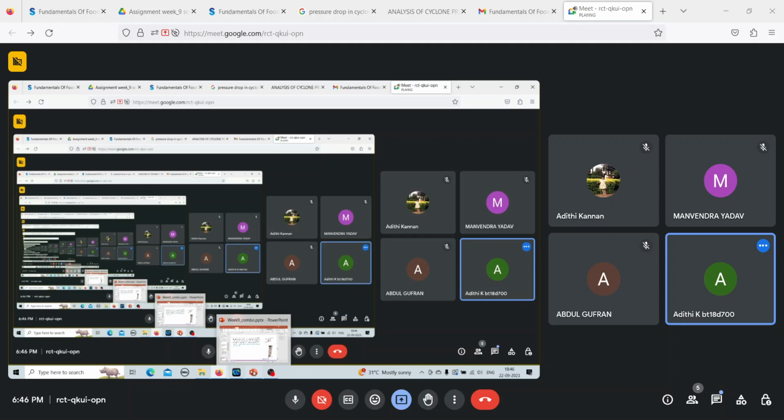So just to give a small recap, upon centrifuging, your liquid will be thrown out towards the walls. So the center will not have much liquid at all. So your liquid is present only from Ri to capital R. So in order to calculate the pressure at the walls, you first calculate the centrifugal force for a small region of the liquid and then integrate it from Ri to capital R. This will give us the pressure at the walls.